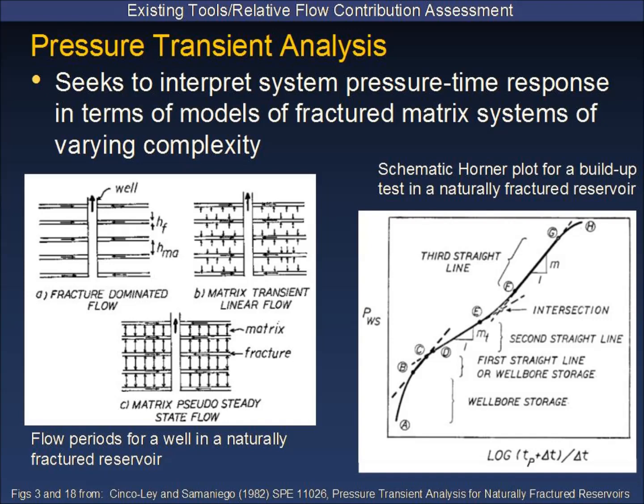Pressure transient analysis, where's Derek? Yeah, there. This is sometimes called well test analysis, and we try to interpret system pressure temperature, or pressure time, or rate pressure time response in terms of models.